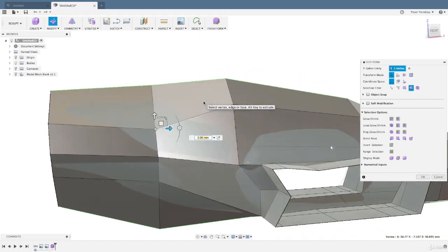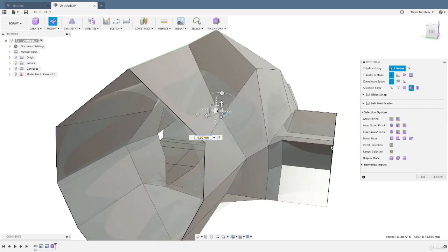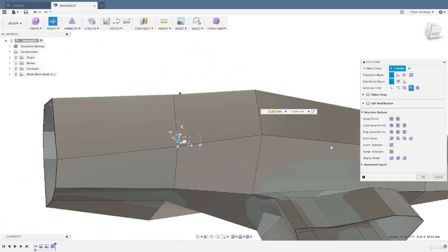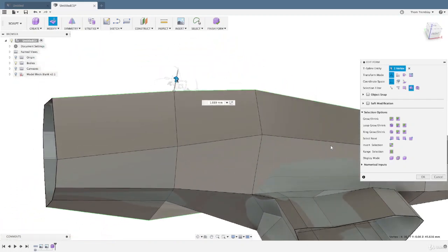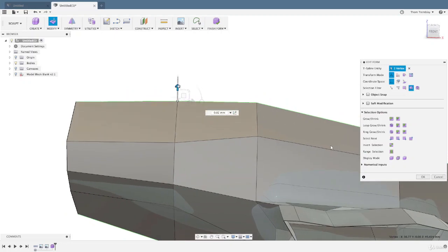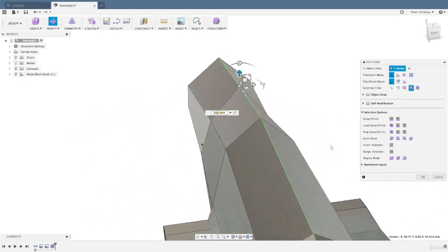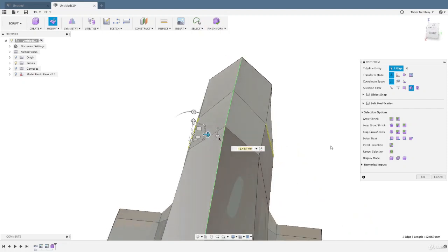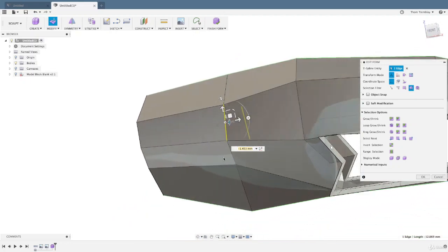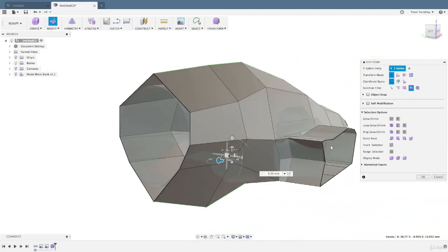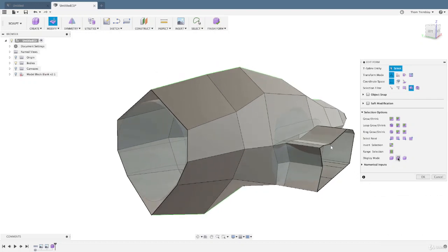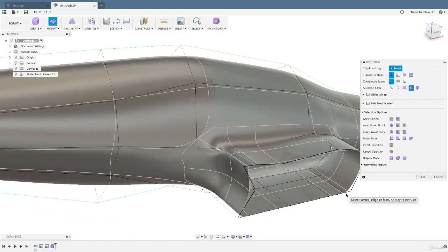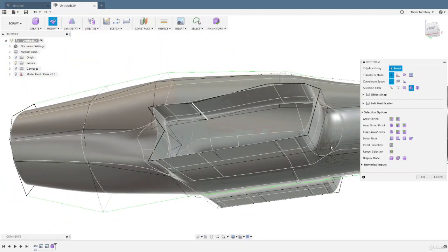Click on the point near the back that is visibly out of line and use the arrow manipulator to drag it along an axis, or use the square manipulator to drag it through a plane. You can also drag the top using the arrow to line up the top of the edge a little better. Then grab the outside edges and move them out just a little bit. Grabbing a vertex near the bottom, you can pull it out to smooth things. Then let's switch to the control frame display. This will give us the smooth body, but keep the edges in place for editing.